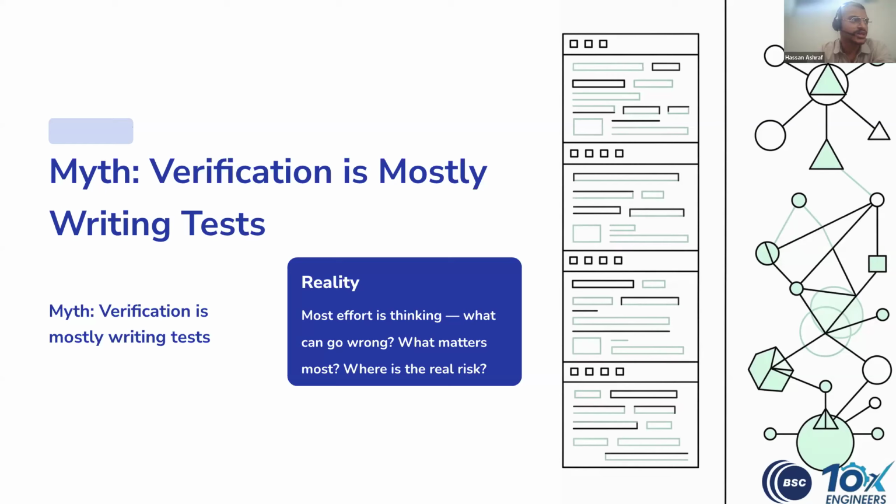They constantly ask, what if? What if this line does not work? What if that condition does not verify? They imagine failure modes designers never considered. They always challenge the assumptions made by the design engineers, and they never use the design piece of code in the reference model, because, as Ignacio mentioned, they can make the same assumption in the reference model, and you can miss the actual bug. The code is just the final expression of that thinking, not the actual job.